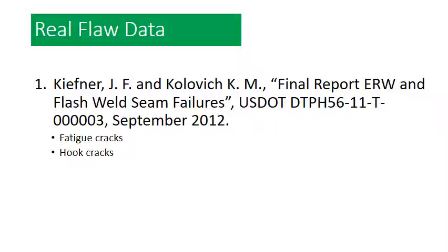Now, I will tell you that for the fatigue cracks, I have included a pi/4 factor applied to the crack depth, and that's to simulate having a semi-elliptical flaw. And that's pretty typical in this sort of business. However, with the hook cracks, I've not included that pi/4 factor. Hook cracks tend to be straighter, and so I've just left the depth as it is, and that's essentially simulating a rectangular crack.